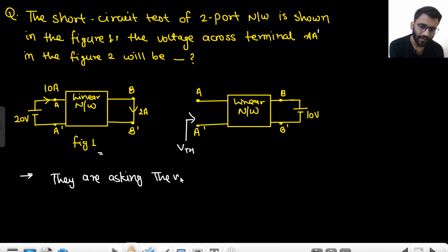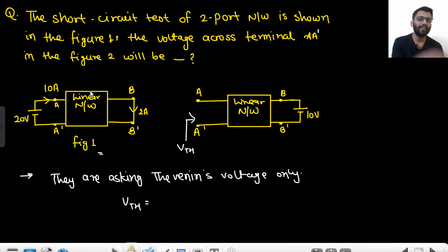Asking Thevenin voltage only. What is Thevenin voltage? Tell me. You can't really find Thevenin's voltage directly, right? Thevenin's voltage is short circuit current into RTH. So first my task is to find ISC, then my task will be to find RTH.